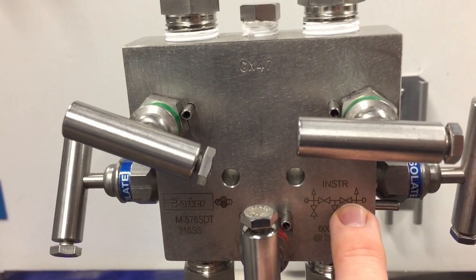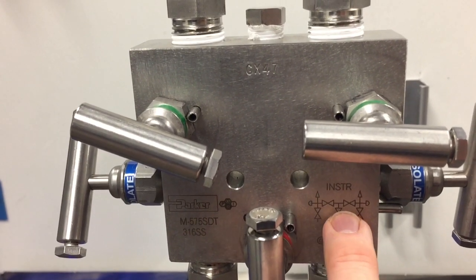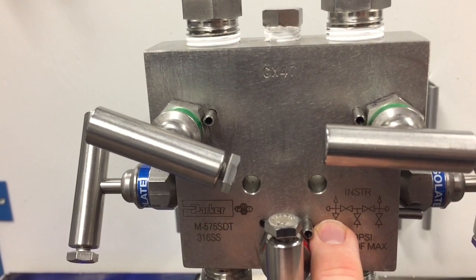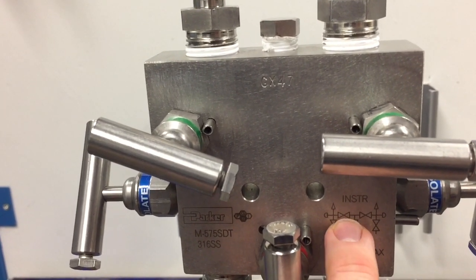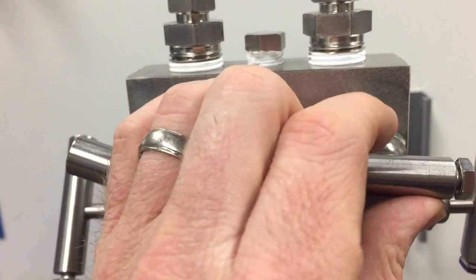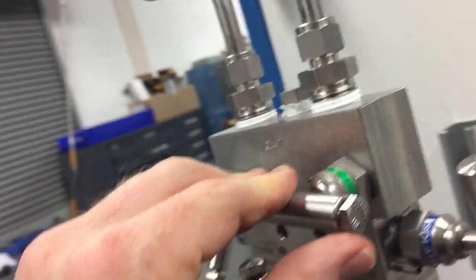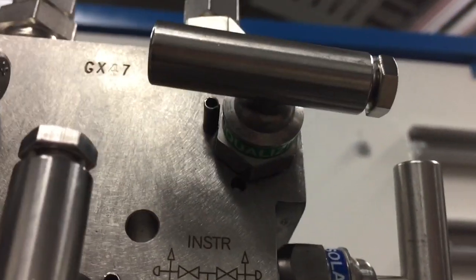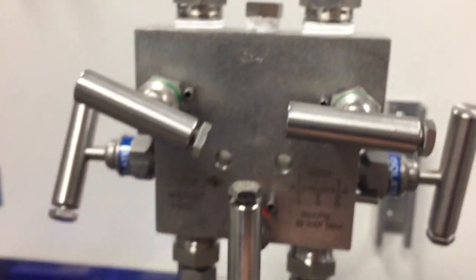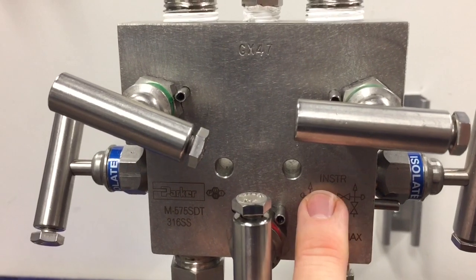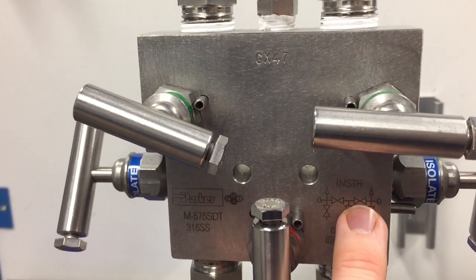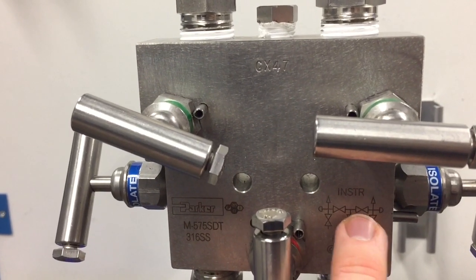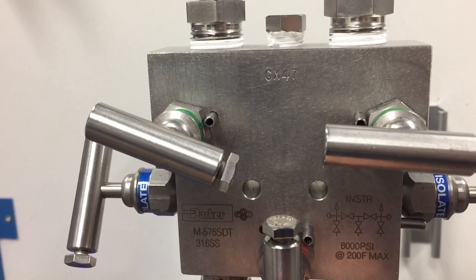And of course we need to have our equalizer valves, this one and this one right here, open as well. So we shut the 2 isolation valves. As long as the equalizer valves, which are right up here, and they should say equalize on them somewhere, you can see it written there. Equalize. They will equalize both sides of the gauge, the high and the low side, right? And so the pressure will be equal on both sides. So once those are open, if we open the vent valve, it'll bleed off all the pressure.